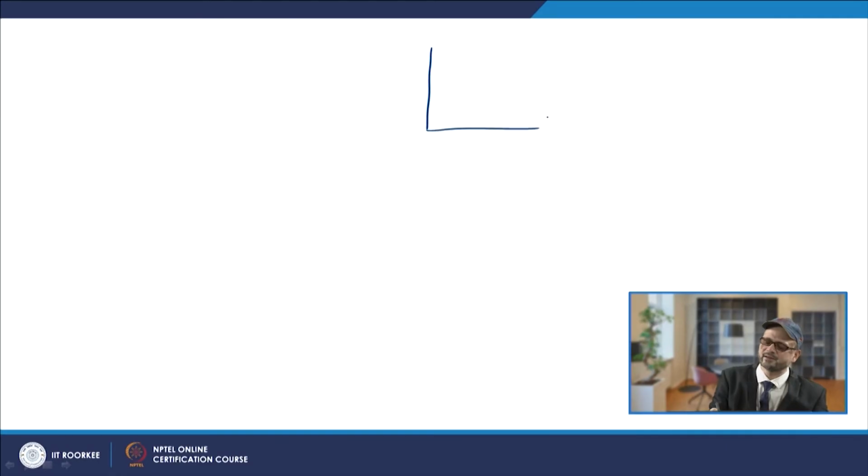This was measured for 1040 steel, and when the fusion zone and HAZ were measured, it was seen that without preheating the zone was a little narrow, whereas with preheating that zone became more wide.